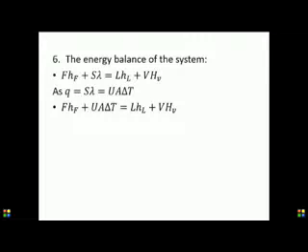For the heat balance, since the total heat entering equals the total heat leaving, therefore heat in feed plus heat in steam equals heat in concentrated liquid plus heat in vapor plus heat in condensed steam. This assumes no heat loss by radiation or convection. Thus, FHF plus SHS equals LHL plus VHV plus SHS, which we can also write as FHF plus Sλ equals LHL plus VHV.